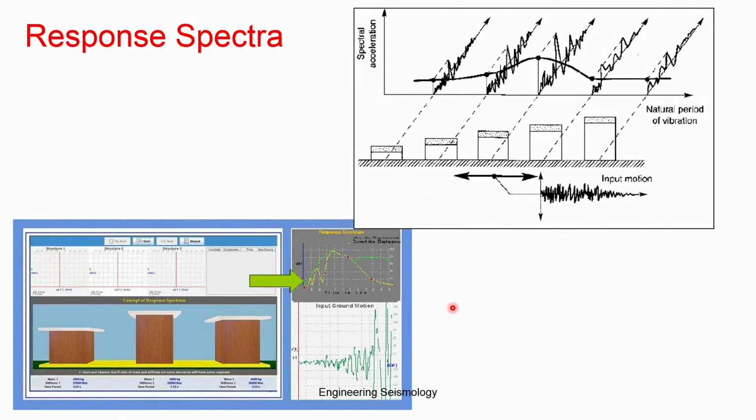So, this Fourier amplitude and spectrum will help to define basically your response spectrum. This is like the response of single degree of freedom structures for a given period for the given earthquake. You can change the period, keep the same single degree, and get a response. That response together, you generate, is called a response spectra.